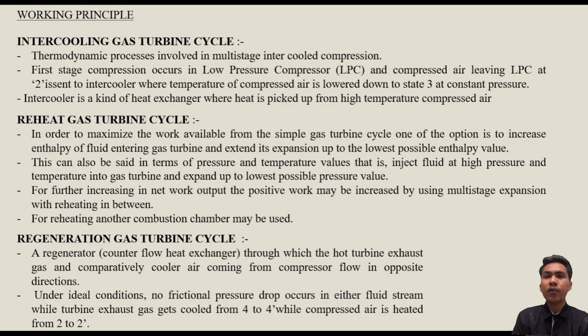The thermodynamic process involved in multi-stage intercooled compression: first stage compression occurs in the low pressure compressor, LPC, and the compressed air leaving the LPC at state 2 is sent to the intercooler, where the temperature of the compressed air is lowered to state 3 at constant pressure. The intercooler is a kind of heat exchanger where heat is picked up from the high temperature compressed air.